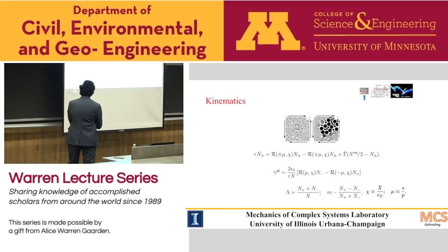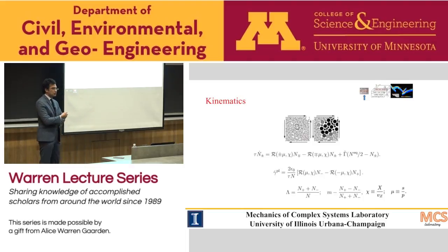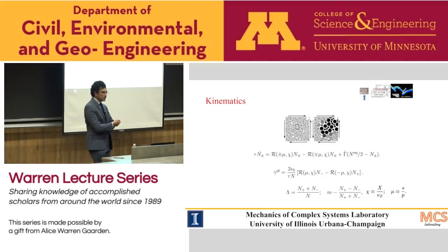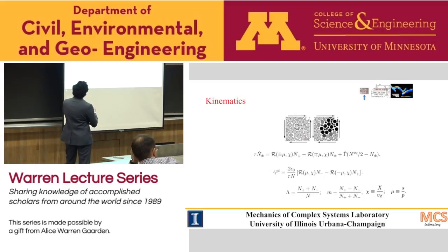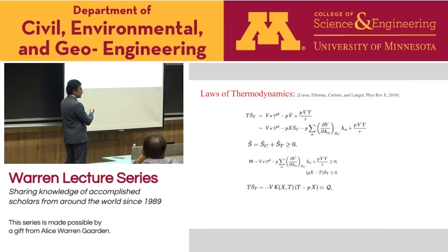And then the theory is driven by thermodynamics. So you could write down the equations of thermodynamics. So this is the first law of thermodynamics, which basically says that you have your conventional external work rate, which is coming from the shear component and the work against pressure. You are also, if we are interested in vibration, then vibration would also provide some energy to the system. And then this energy has to balance with the dissipation or the heat. So that is the heat of the system. That is the thermal energy.